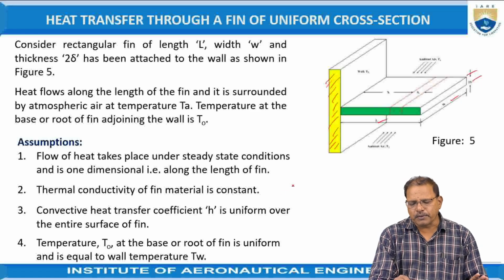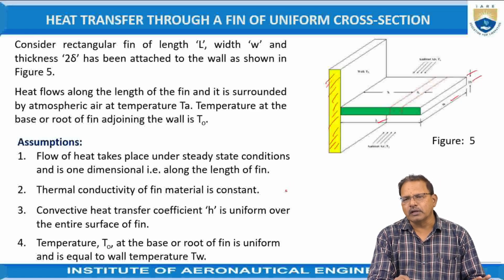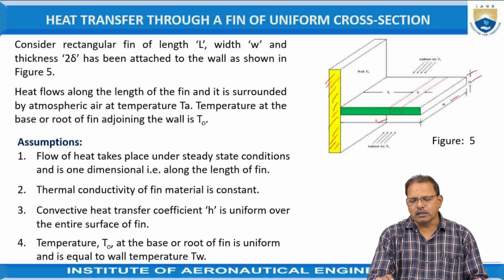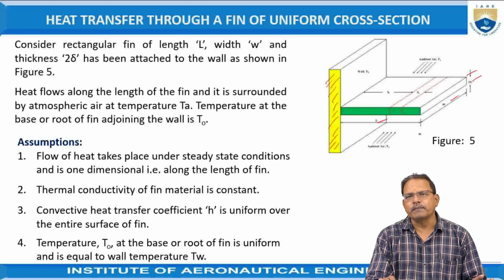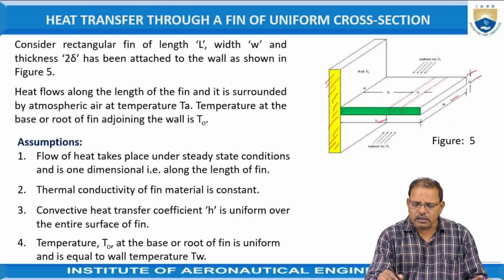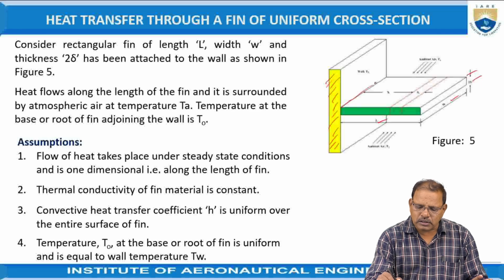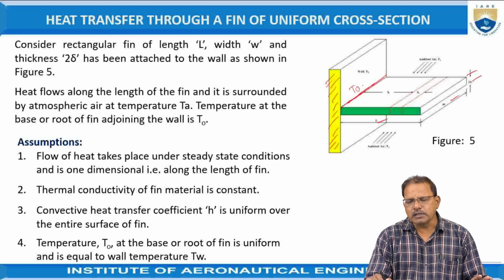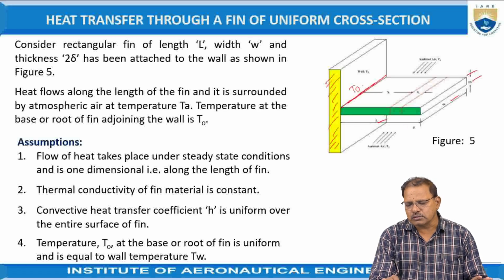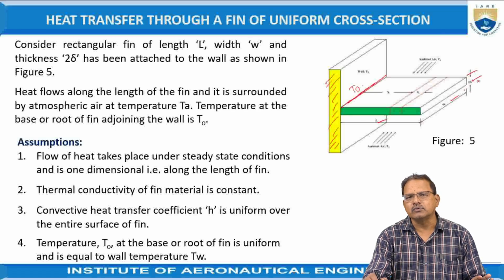The temperature should be dissipated to the air in order to maintain this body at normal temperature. Here a fin is attached to it, in the form of a rectangular shape perpendicular to its surface. At the junction of the fin to the surface, assume the temperature is T naught. The dimensions of the fin are length equal to L, and width and thickness equal to 2 delta.